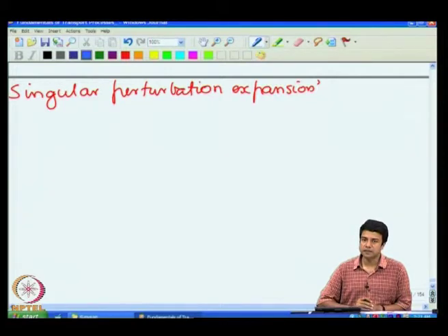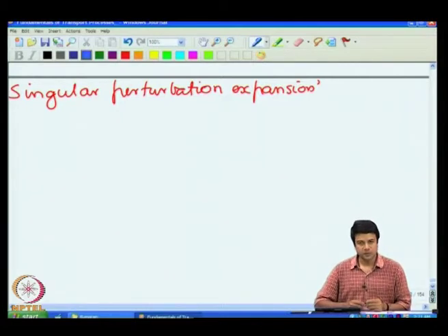There is no convection perpendicular to the surface, because the normal velocity at the surface has to be identically equal to 0. So, the velocity has to come to 0 at the surface. That means there cannot be convective transport perpendicular to the surface. Ultimately, transport perpendicular to the surface has to take place only due to diffusion.